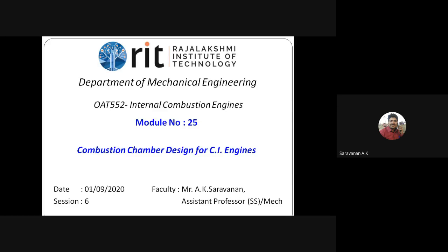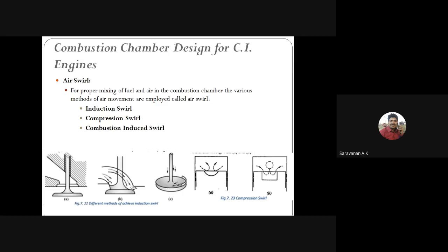In CI engines, during the suction, induction, and compression process, the only working substance is air. Only the air is sucked in and compressed, and the fuel is injected through the injector at the end of the compression stroke. So the time available for vaporization and mixing with the air is very limited.